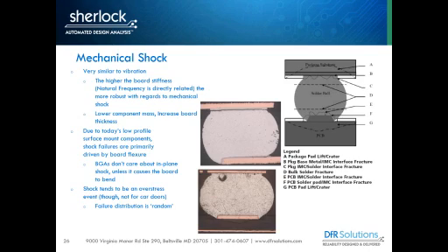So what you'll see is that when you have a shock-related event, you'll cause sort of mixed mode failures, where the failure site may be bond pad cratering, or it may be intermetallic fracture. So here's an example of intermetallic fracture, where in this case, this is a tin nickel intermetallic, which fractured.